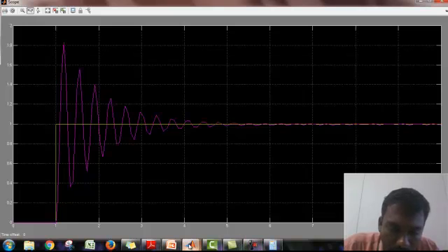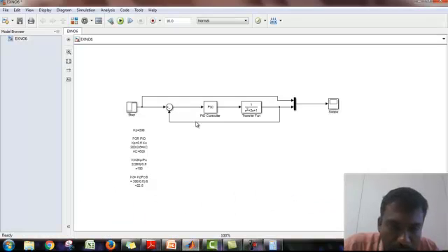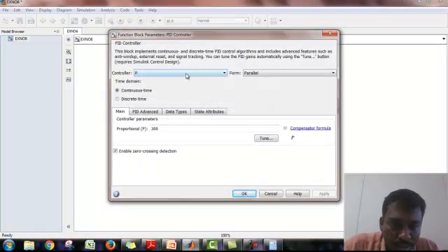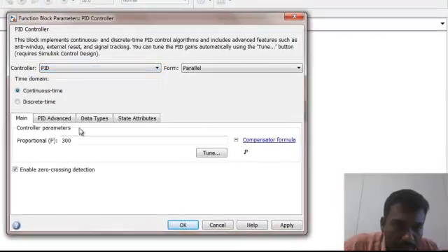Okay, in the calculation I did previously, for KP 300 you're getting PC as 0.6. So once we know these two values, you can find all the remaining values and apply the same values by changing the proportional controller to a PID controller. So what happens? We can find the response and go for PID.